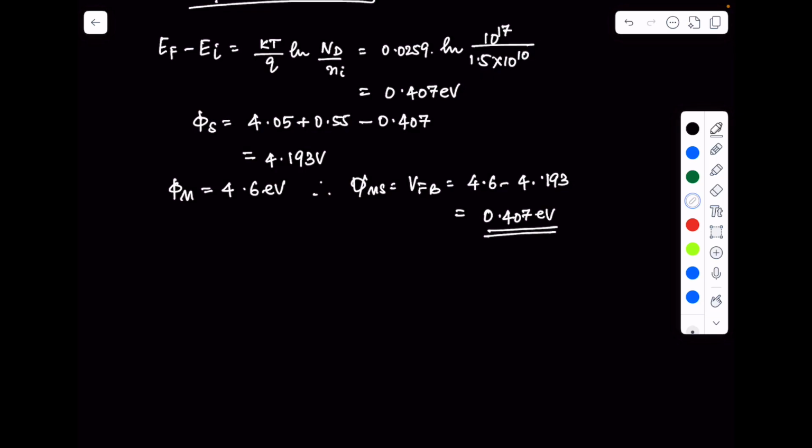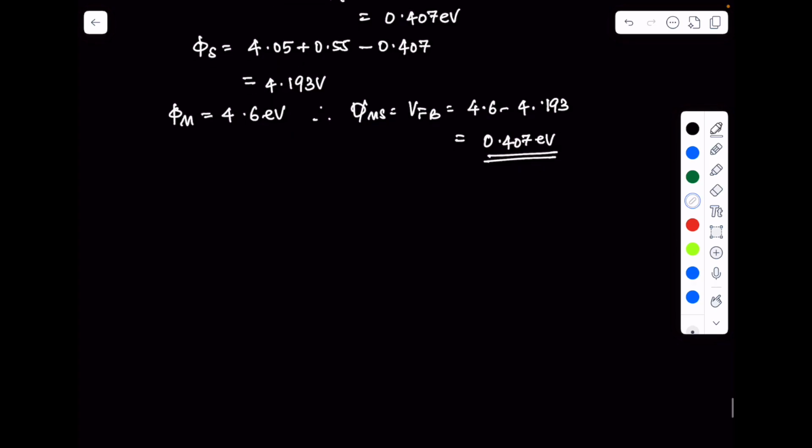Right? So that is roughly your flat band voltage. And so therefore, if I look at Vt, this is a PMOSFET, so my Vt is given by phi_ms minus 2 phi_f. Again, I'm treating phi_f to be a positive quantity, minus square root of 2q epsilon_s into 2 phi_f, divided by Cox. And this has to be equal to minus 0.5 volts.